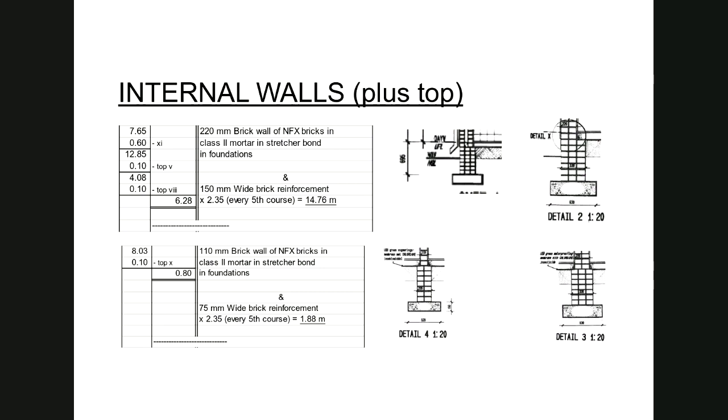Okay, so then getting back to my internal wall, the last detail that I now need to deal with is the top-up part for the detail 4 that has a half brick wall in that position. Please just look at the lengths of the walls, and I want you to go back to your collections to make sure that that is actually correct. So where I'm using the top up, that is not influenced by the wider foundation walls at the connections. So I'm using the length of the superstructure wall.